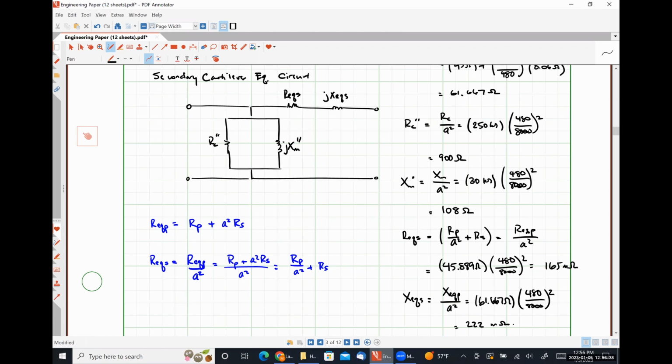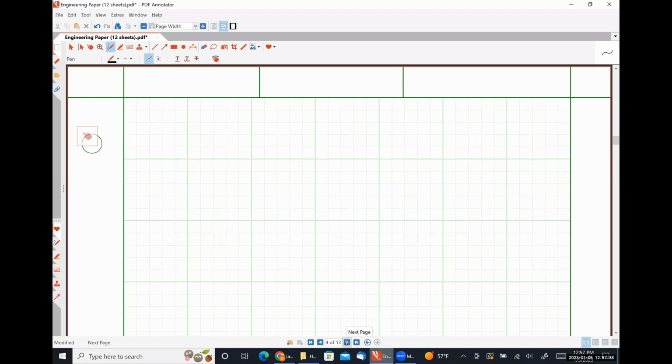Okay? So there are two tests that are carried out. We have an open circuit test and a short circuit test. Now, I want to say something here because the book that we are using, the official textbook for this class, in the practice problems and things like that, effectively everything is referred to the primary or high voltage side. That being said, in actual industrial practice, the open circuit test is usually performed on the low voltage windings, and the short circuit test is usually carried out on the high voltage windings for safety reasons, okay? So I'm going to work an example under that constraint, and we're going to talk about things when we derive it. And then I just want you to be aware that a homework problem I'm going to give you straight from the book might be slightly different. And so I want to talk about where those differences are going to come in. Okay. All right. So let's talk about the open circuit test first.